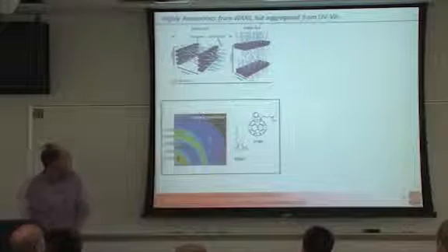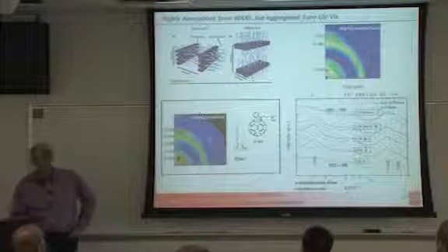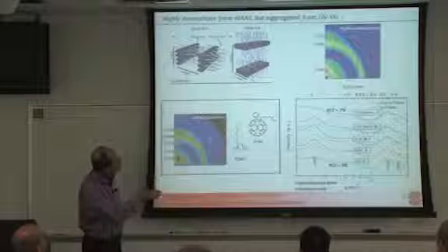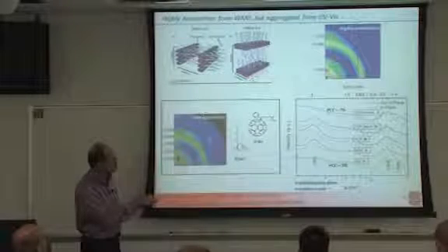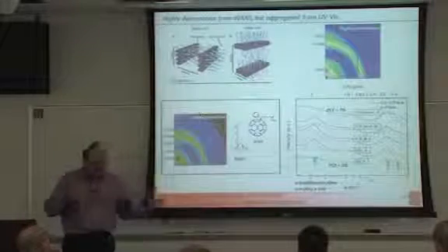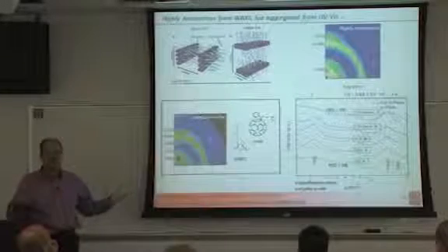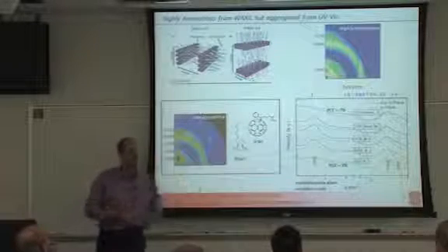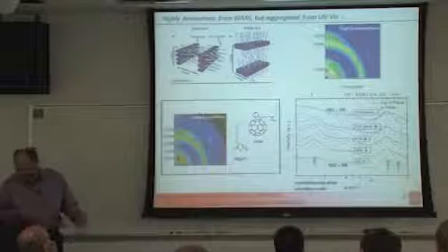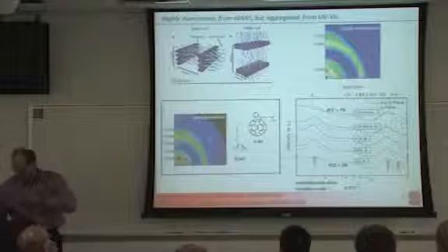All right, so now back to the WAXS. The P3HT was semi-crystalline, and we look at that in terms of the WAXS, okay? And you see there are too many peaks in here. So even as a function of solvent, it's not a highly crystalline material. It's relatively amorphous. The size scale doesn't seem to matter. So the composition fluctuations don't seem to matter. So this really flies in the face of a lot of the assumptions that the field has, that high crystallinity is good, et cetera, et cetera. So what's so intrinsically good about this material?